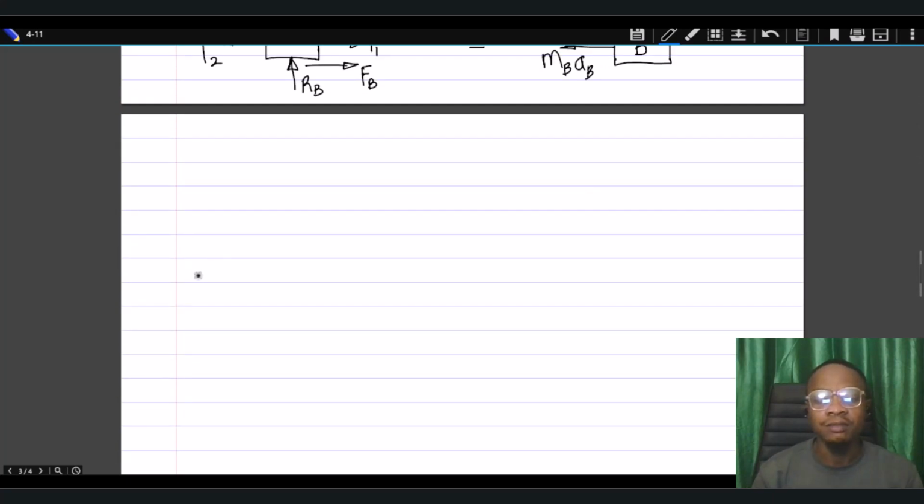So we have a 45-degree angle here. Then we include the block C. Then we have the normal reaction from this surface, which will be perpendicular to this surface. So we're calling that normal reaction R on C. Then this moves down the incline, so the frictional force on this will be up the incline. So we can have that as the frictional force on C. Then we have the weight of this body, which will be vertically down. So we're going to have something like this.